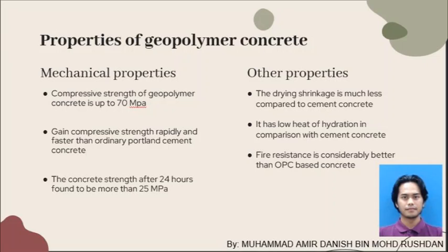Next is about the properties of geopolymer concrete. The mechanical properties. The compressive strength of geopolymer concrete has been found up to 70 megapascal. The concrete gains its compressive strength rapidly and faster than ordinary Portland cement concrete. The concrete strength after 24 hours has been found to be more than 25 megapascal.